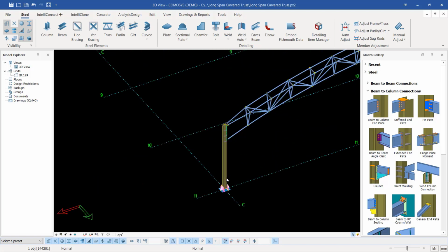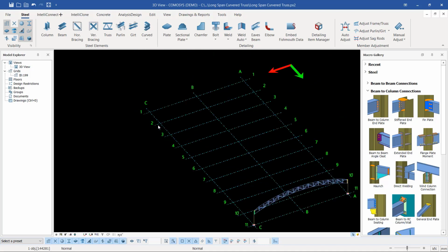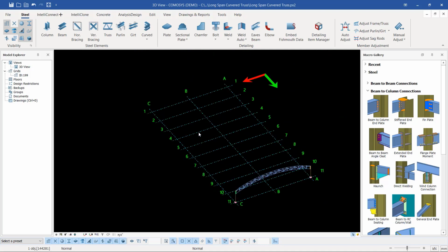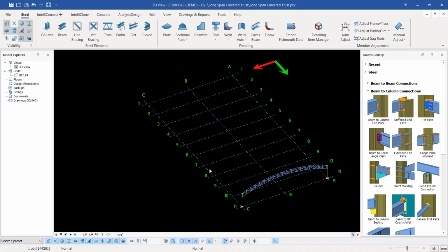And to populate that, first of all, you have to confirm how many bays do you have along your axis or along your full length of your structure. So as it is now, we have 1, 2, 3, 4, 5, 6, 7, 8, 9, 10. We have 10 bays, and how many columns we have? Approximately 11 of them. You can see 1 up to 11 here. So by default we have 1. So the number we have to add is only 10.